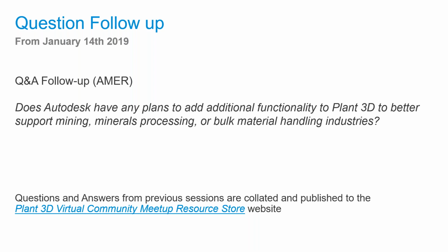I also want to mention the audit command in general, with AutoCAD PNID drawings. If you have any type of corruption with a PNID drawing, there's not a plant audit for those drawings, right? So the regular audit command, we've been told by the development team, does a little bit more with a PNID drawing. And I've actually seen that fix some issues before with tags and just objects in general. But it's not really specifically documented. It's just something to keep in mind if you have an issue with a PNID drawing in a plant project itself.